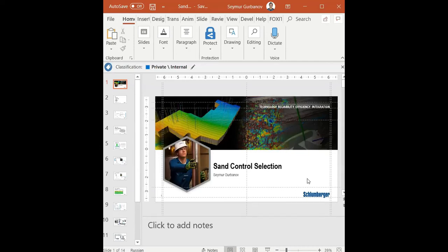Which simulation software has been used to conduct this study? Haris from Pakistan. So Schlumberger has its own web-based software. Its name is the Sand Advisor. Basically, we input the PSD test results, and it calculates based on the equations from the SPE papers. It gives us those quantities, so we know how much sand we'll produce.